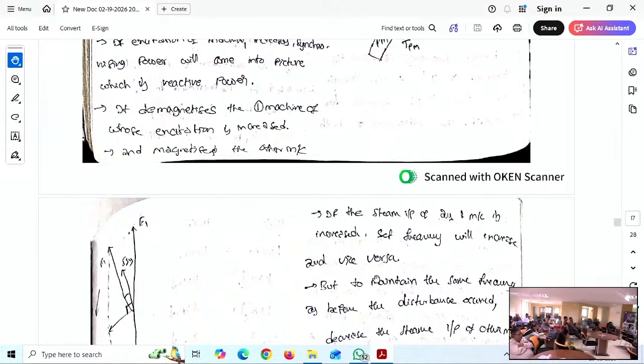Correct, exactly. Because this is called set voltage. Parallel operation requires conditions to be satisfied. Rated voltages must be the same, need not be 400 only. 400 is our requirement, because for the V reference phasor we are fixing the line voltage at 230.